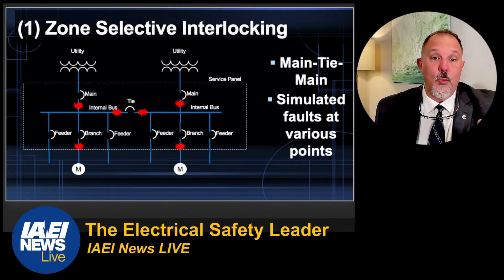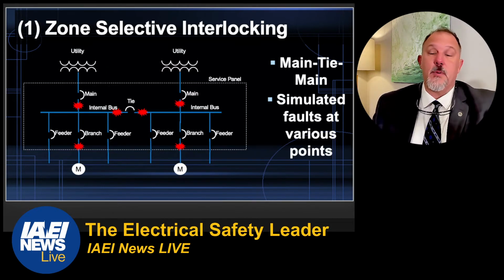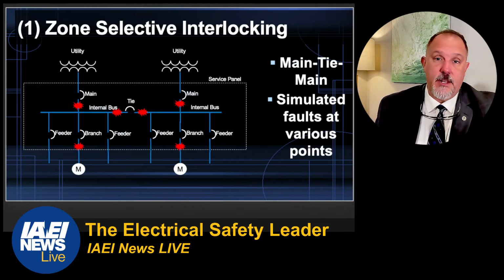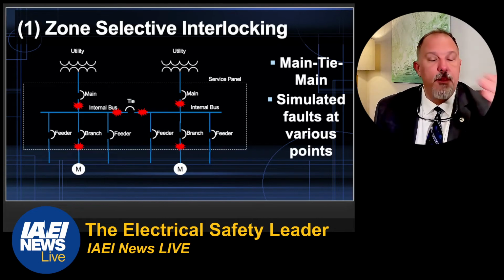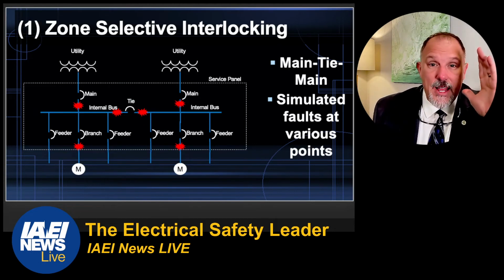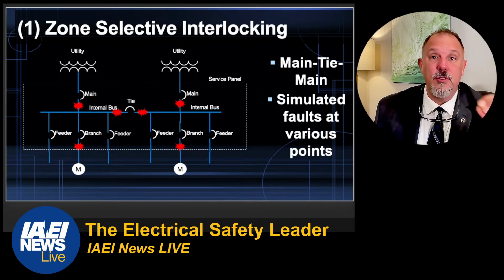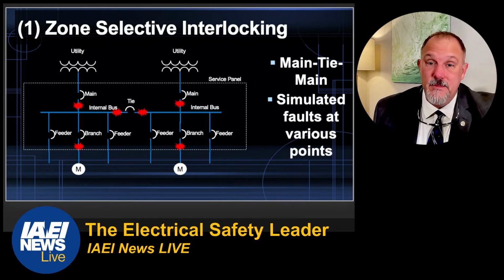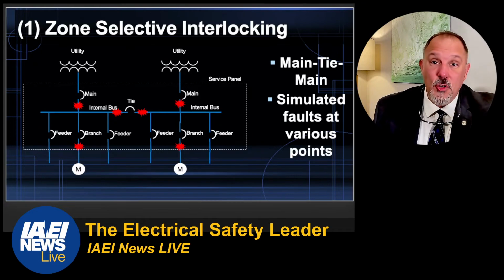And when you're putting this equipment in, this equipment probably is going to have other relays. It's going to have a lot of different technologies on it, and there will be a commissioning service. You're going to get someone probably from the factory of the manufacturer to come out, sit with a computer in front of that equipment and run through all the diagnostics and make sure everything is correctly wired and installed before you do what? Before you energize.